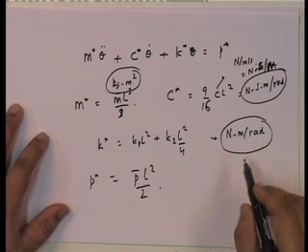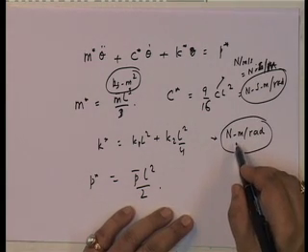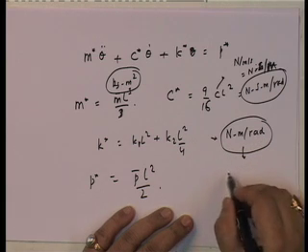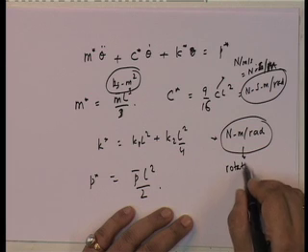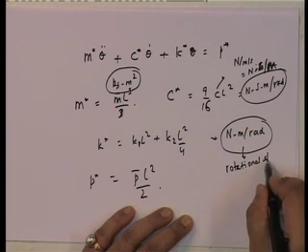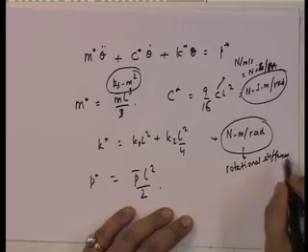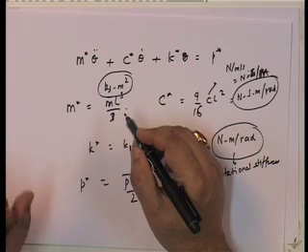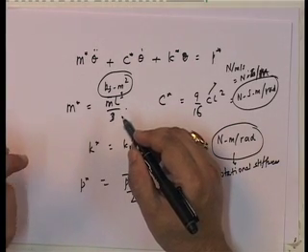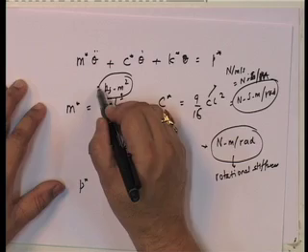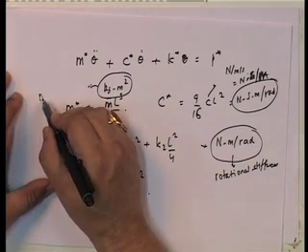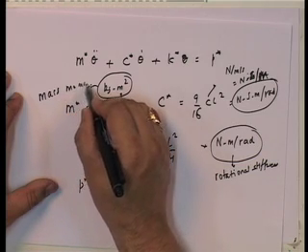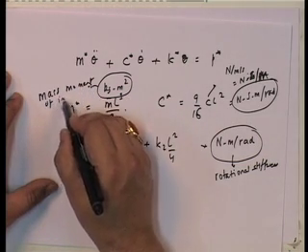If you look at all of these, what is Newton meter per radian? Moment per unit rotation. That is like a rotational stiffness, right? What is this? Kg meter squared, mass into distance squared. If you remember from your old high school, it's mass moment of inertia.